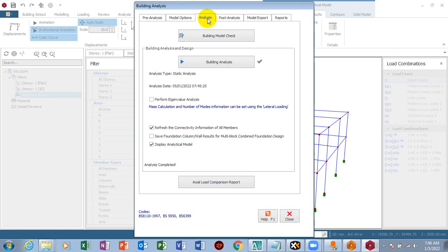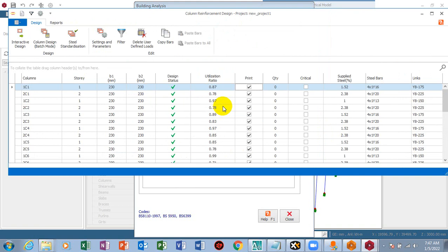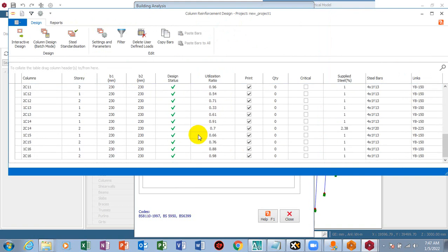Instead of the normal 450 depth, it can increase to 500. Then if, when you try increasing the depth, it's still telling you that it's not sufficient, you may have to change the thickness of your reinforcement. Once you increase the depth and change the thickness of the reinforcement, it will most likely pass.